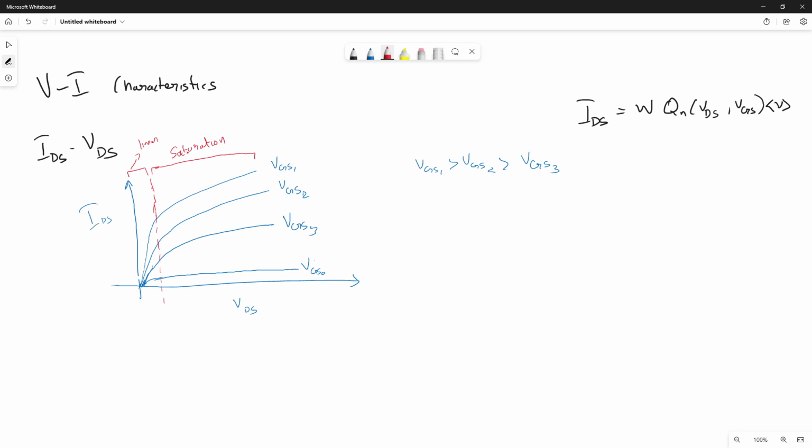So this is the linear or the ohmic region and the saturation region, and the other region of interest is the region below here. This VGS not that I told is essentially what is called the threshold voltage. The threshold voltage is the voltage at which my channel becomes capable of conducting. Below that, my channel is not suitable for conduction of electrons from the source to the drain. So the region below that is referred to as the subthreshold region.